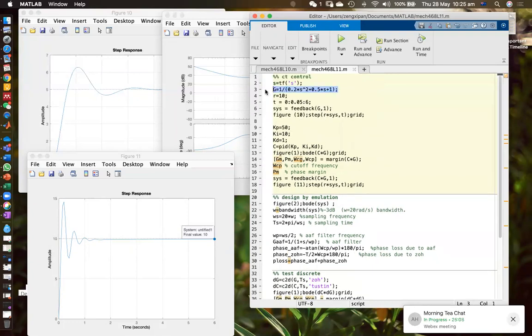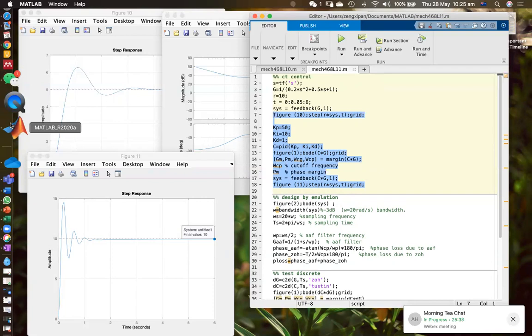You can get a model from examples from other websites or other cases, write a story about that. Then design the controller. So PID is just one way. You can do other controllers as well. There's no limitation here, but probably you just go with PID because that's what I use as example. You're probably more familiar with that. So in this case, say this is a good controller, and the phase margin is 26 degrees. I remember that value, 26 degrees of phase margin.